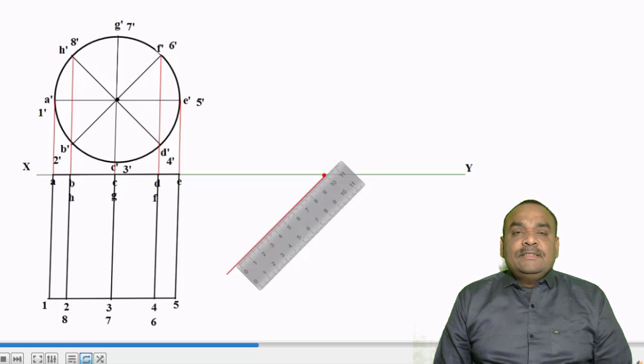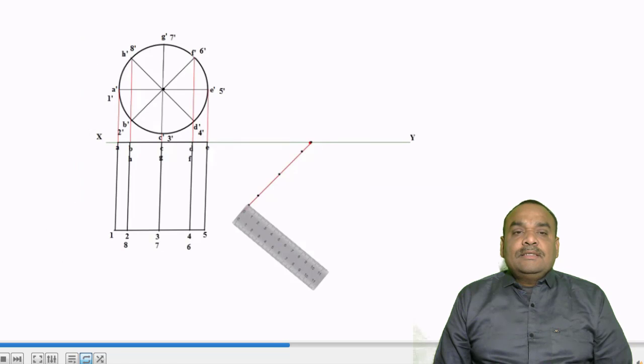On the inclination line, first we mark our ABCD base with the same dimension as the first stage. Either you can say you are going to arrange your first stage top view with reference to XY here. So I choose the appropriate distance and mark on my inclination line. So that is your points, and again you create the same rectangle with 100 mm dimension.